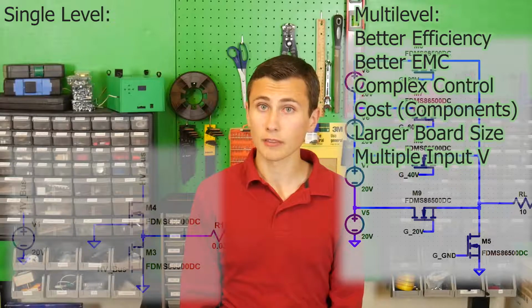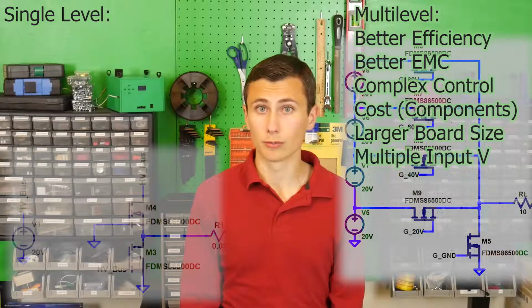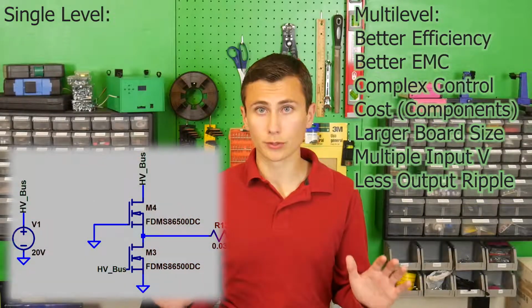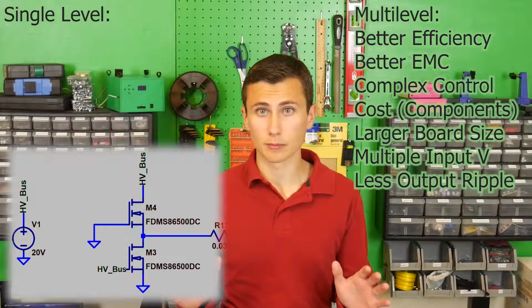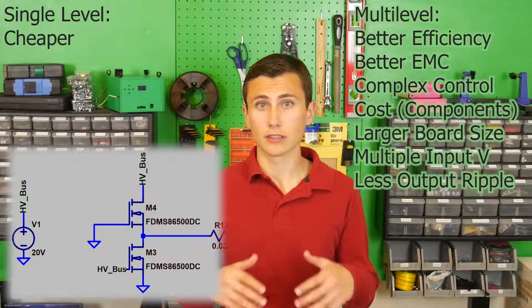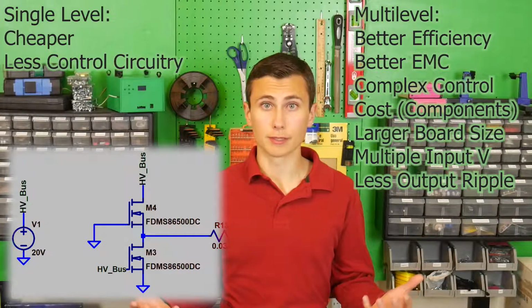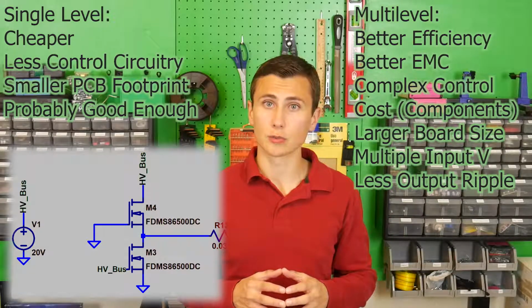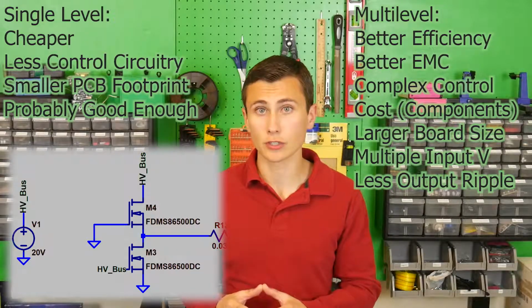Since some of the largest benefits of the multi-level inverter topology over the two-level are improved efficiency and lower output ripple, let's move forward with the two-level filtered H-bridge topology for our proof of concept platform. This will give us a chance to evaluate the ripple and efficiency of the topology. Then we can decide whether the complexity of the multi-level topology is warranted given our ripple and efficiency requirements in the future.